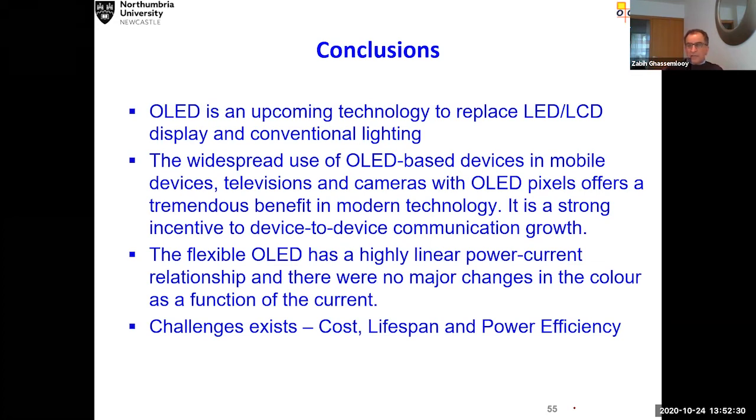Their power-current characteristic is very linear with a wide dynamic range, and that is wonderful for multi-carrier modulation schemes like OFDM, because OFDM is very sensitive to the linearity of the antenna. If you can make that linear with a wide dynamic range, it means you can handle the very high peak-to-average power ratio in OFDM. That's exactly what you should have.